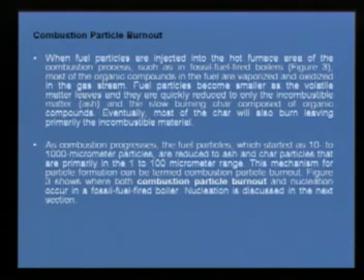As combustion progresses, the fuel particles, which may be larger, they started as 10 to 1000 micron particles from the coal mill, are reduced to ash and char particles that are primarily in the range of 1 to 100 micron. This mechanism for particle formation can be termed combustion particle burnout. Well, I don't know if you have the figure here.